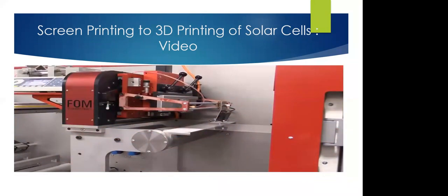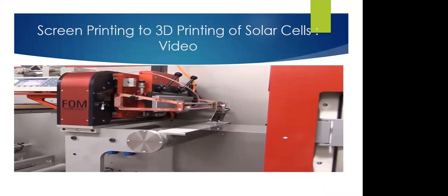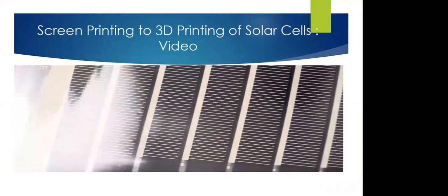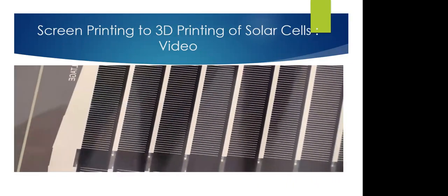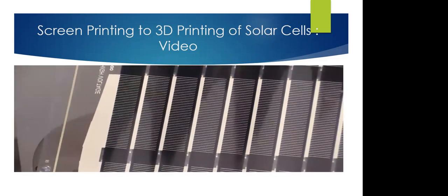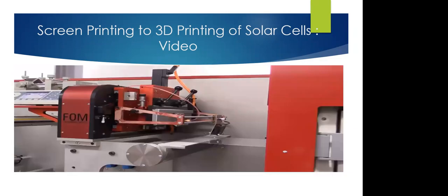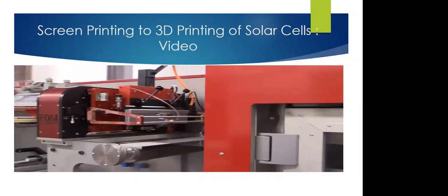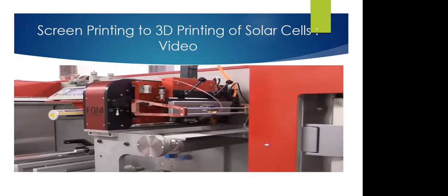So in order to put down continuous films, we use a technique called slot die coating, in which a continuous curtain of film is deposited onto your moving substrate, allowing for uniform thin strips to be printed. The head that we have connected right now is a 13 millimeter stripe head, but we can do anywhere from 10 millimeters up to the full 300 millimeter substrate width.